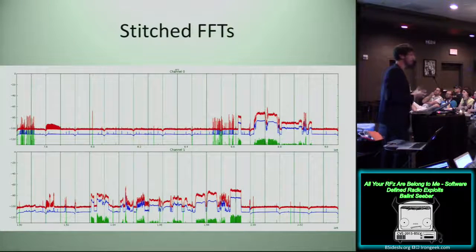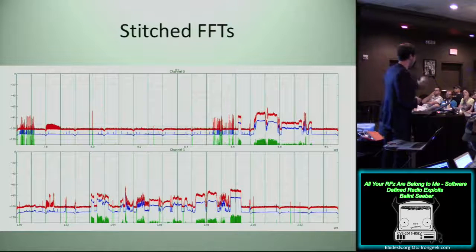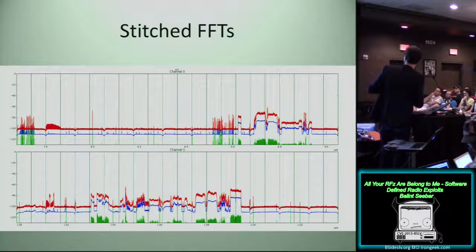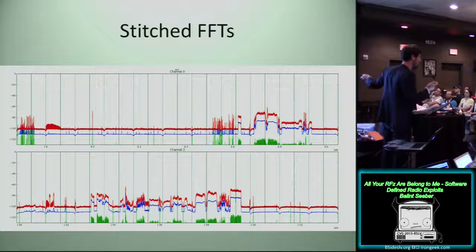So this is just like a generic tool for looking at the radio spectrum, and what's nice is that as you end up doing this sort of sequential scanning, you can store these individual captures, and then you can stitch it into one really, really wideband FFT. So here we're looking at the two regions of the cell spectrum allocated.